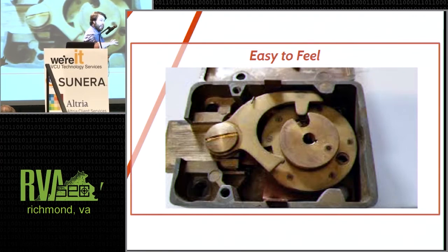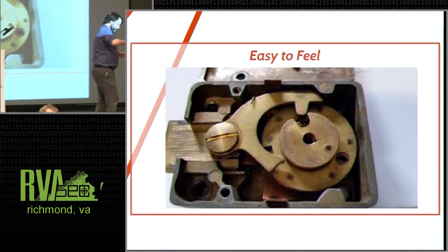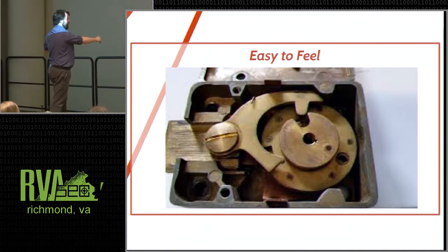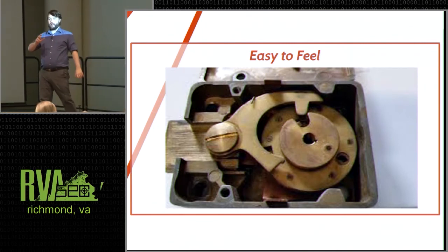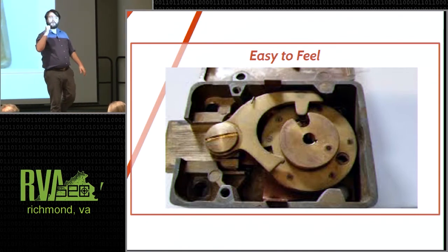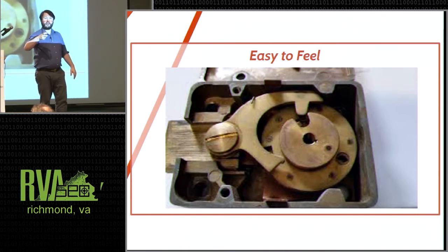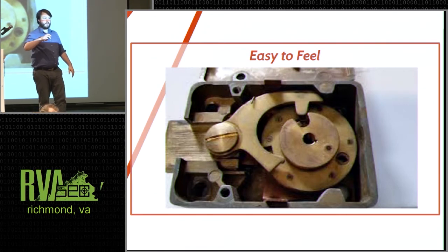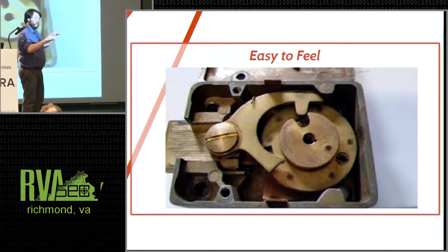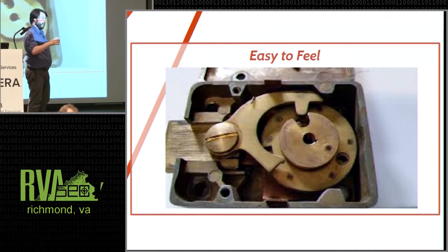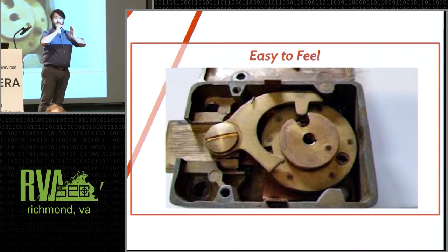What you're going to do is take all of the wheels in the safe, turn them, and park all of them at some number. We'll say we're going to park everything at 40 right. We're then going to turn our cam wheel with the dial back around until we feel that nose click into place. Because the nose will dip down as it approaches its gate. And if you can measure where you first hear the nose touch the gate, and then where you next hear the nose touch the gate, or feel it, you know how far the fence has descended.